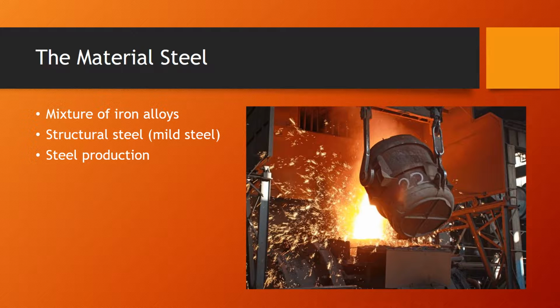Steel is created by a process beginning with smelting, then using the basic oxygen process. Carbons and other impurities are burned off. Metallic elements are added to eventually create a finished quality of steel. The process takes less than an hour. Most structural steel is made from recycled material today.